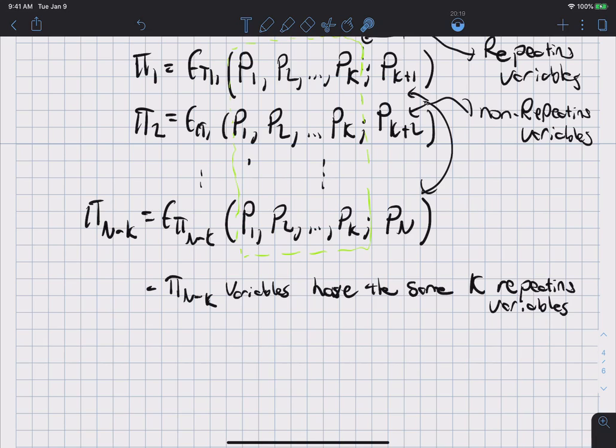Now the question is, if our drag force is a function of 6 different things, and k is equal to 3, how do we pick P1, P2, and Pk? To some extent it is a little bit arbitrary, but there are some rules to pick these repeating variables. Some are hard, rigorous rules based on Buckingham's theorem itself, and some are just based on good engineering practice and experience.